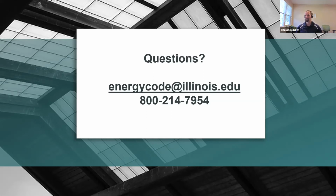For builders that aren't necessarily familiar with air sealing, like a new builder who just started their company, it's a good way to learn about where common issues are. And a lot of the issues we've covered are common leakage points in both commercial and residential buildings. I see a lot of drop ceilings and interior soffits as very common air leakage points in both building types.